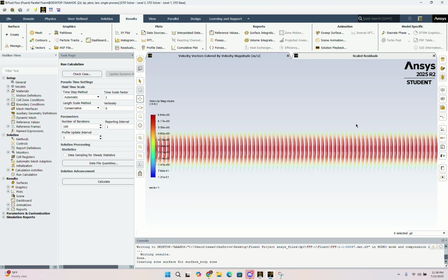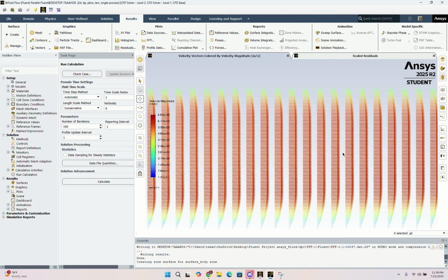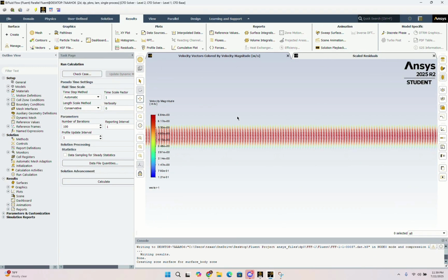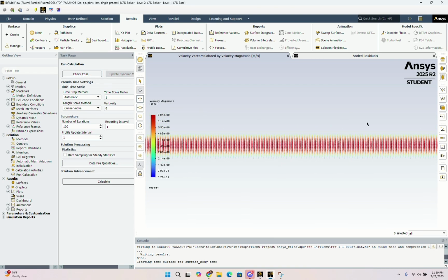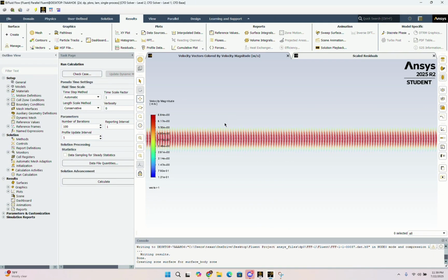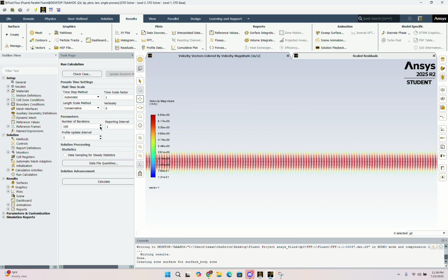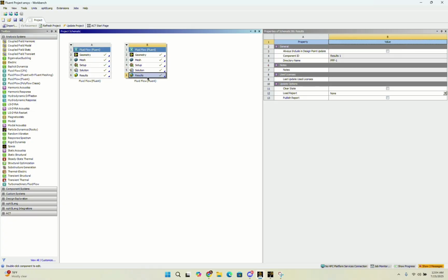Now we're gonna go to the left side, and that's gonna show how at the beginning the velocity goes like that, and then it just goes inward with the boundary layers. Since the velocity at the top wall is moving, there's gonna be more velocity at the top than there is at the bottom. As you see, it's slower at the bottom since it's stationary. I go all the way to the right side, and as you go, it gets slower towards the bottom, but it speeds up in the middle. Okay, if we zoom in, super right in the middle, that'll be later. You'll see our max velocity.